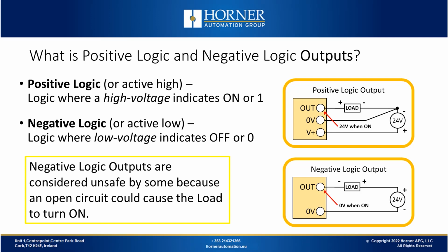It is sometimes said that negative logic outputs are somewhat unsafe because if the negative wire connecting the output module to the load were to fall off, then potentially the load would turn on because of the external connection of the plus voltage to the load. So that's one of the reasons why negative logic outputs aren't used too often anymore.